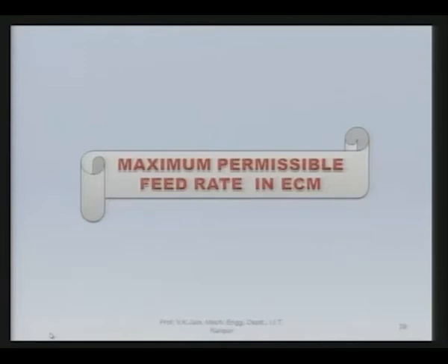Both these equations are used in the calculation of theoretical electrochemical machining. But the equation with finite feed rate has certain drawbacks. It takes many iterations before one can arrive at the correct inter-electrode gap, and in the finite element method or finite difference method, there are a large number of points at which these equations are to be evaluated. So, a single equation applicable for both the cases and taking very less time had been proposed, and that was discussed.